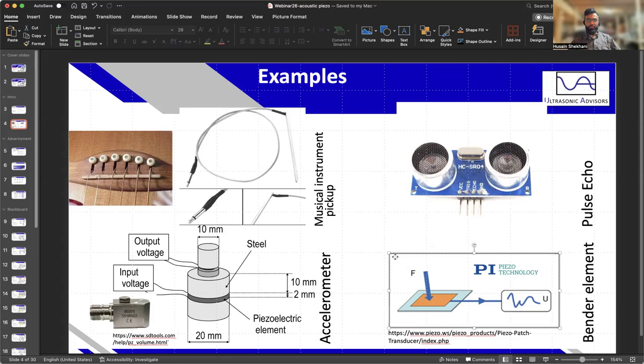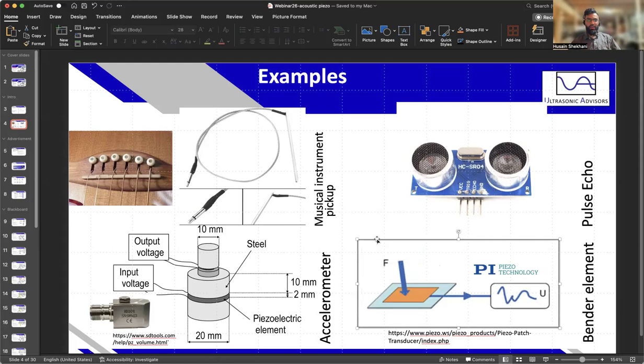And you can also just find plain elements and slap them on a piece of substrate and start measuring stuff. Like you attach a bender element, or these softer patch elements, which can generate enough voltage based on almost any stimuli to create a frequency response, or something that you can just measure. Benders are very common with sensors because they exhibit much more displacement than solid elements. That's something you'll see in most cases, because the design of actuators is very different from sensors.